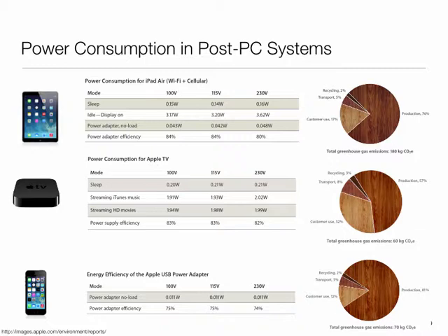So part of what you are paying here is that smaller devices and simpler designs are also leading to less efficient power supply systems. So that's the adapter efficiency. Then you have a second hit on efficiency: we use a power adapter which is less efficient, charge the battery, and then we draw from the battery, but the battery has leakage. So your overall end-to-end power efficiency is probably taking a significant hit between these two elements: the adapter is less efficient, and then I'm losing energy from leakage in the battery.